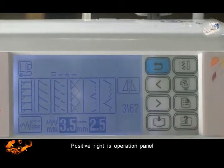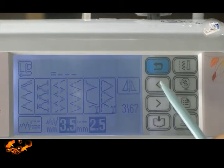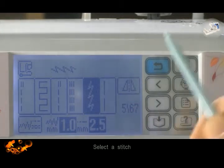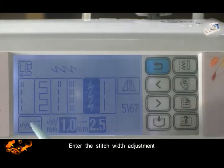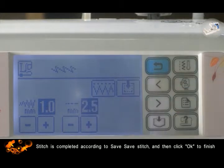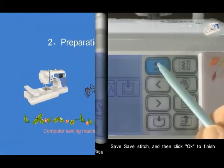Facing the front is the operation panel. Here are the forward and back page buttons. On the left is the LCD screen. Select a stitch. Press flip horizontal to reverse it. Enter the stitch width adjustment, and press add and subtract to change the numbers. Stitch length adjustment, likewise press add and subtract. When the stitch is completed, press save stitch, and then click OK to finish.